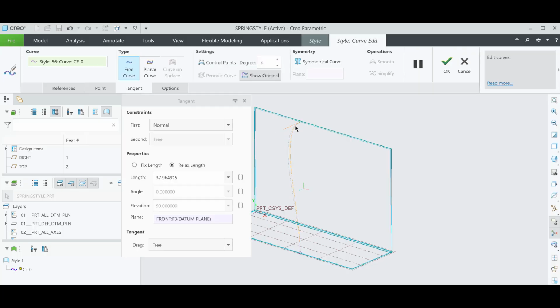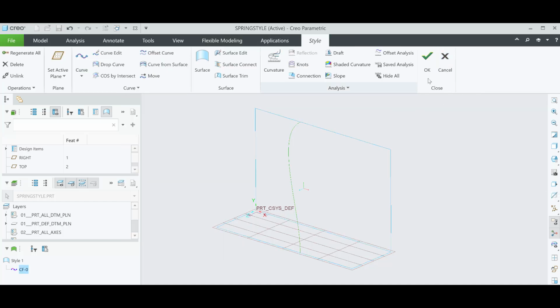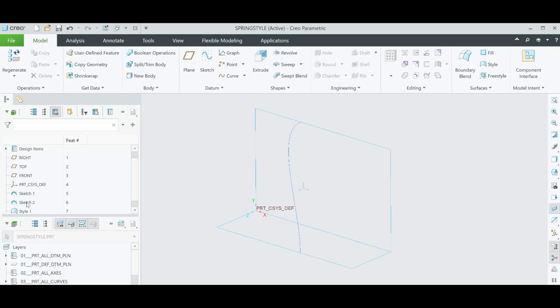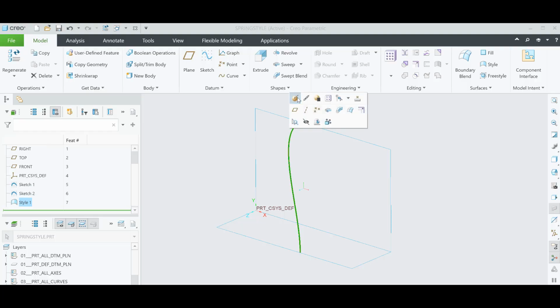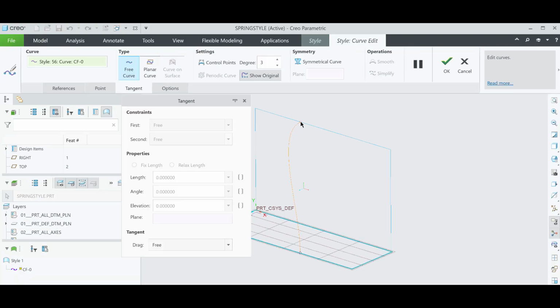This is a non-traditional kind of thinking that you can make parametric. If I can type in a number here, it's technically parametric, but that's not the traditional sense. When we think of parametric geometry, we should be able to left click here and get the edit function. Notice when I left click, I don't get the edit function in Style. So I'm going to redefine the curve, double click on the entity, and then push out this variable so that